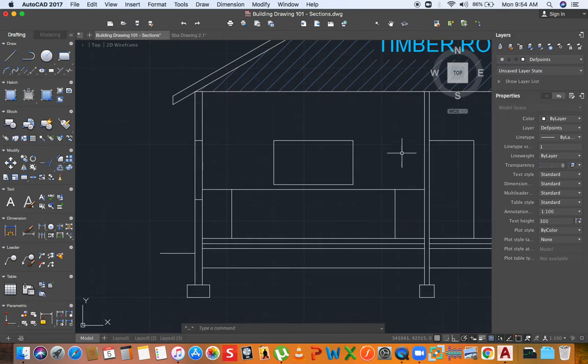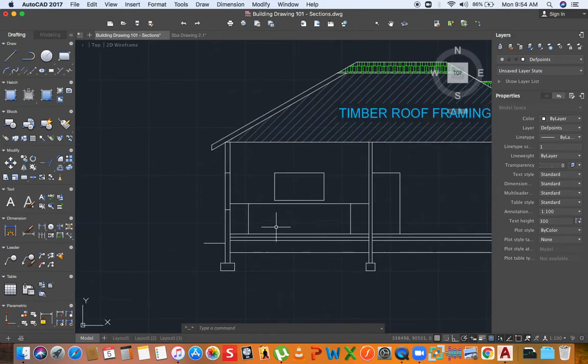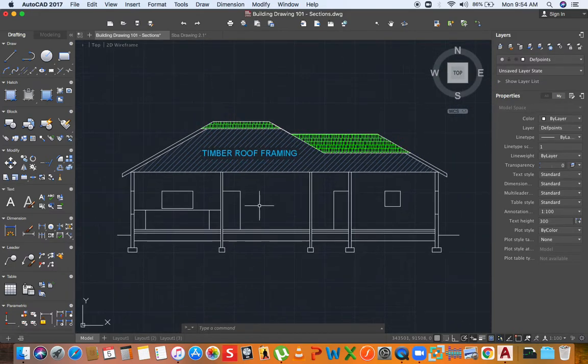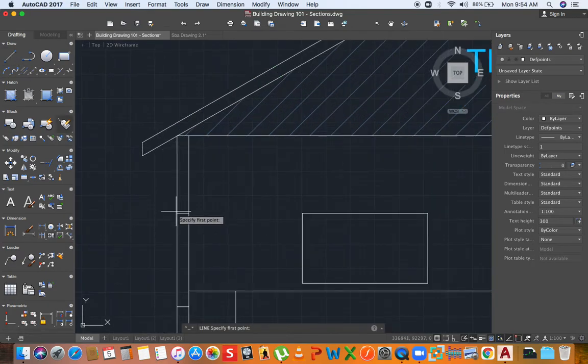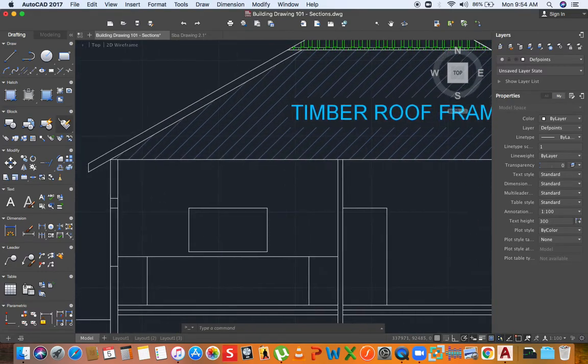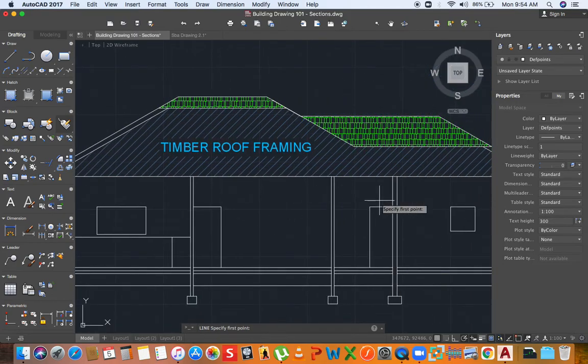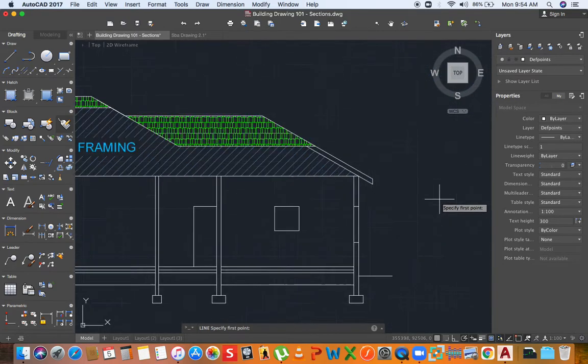There's a fridge here, so you should draw the fridge in front of the counter here, and you can now draw the cupboards and all of that in here. Right, so this is basically how you draw it. There are some things that you should put over each window or door that is cut through. You have got 200 millimeters of height. There's none here, so you don't have to put it here. There's none here. Only on the other side.